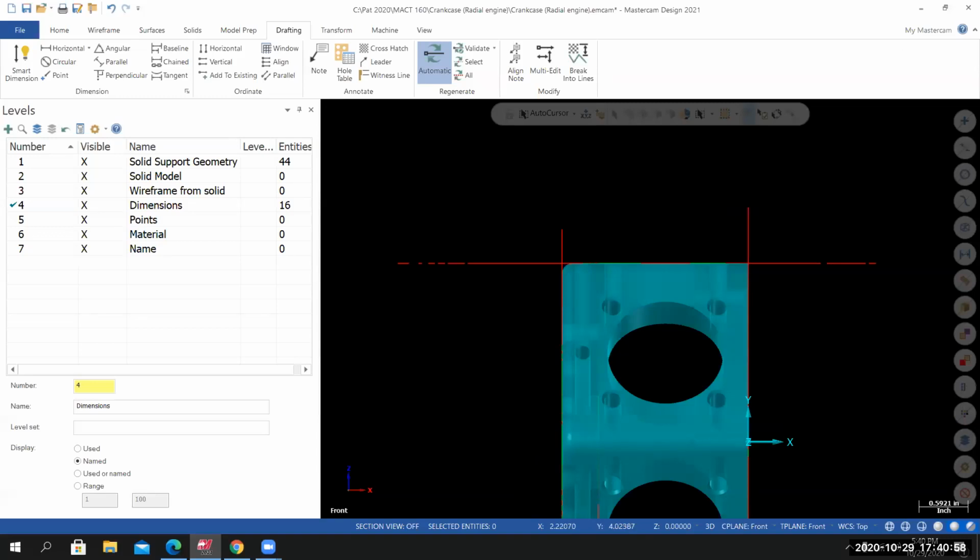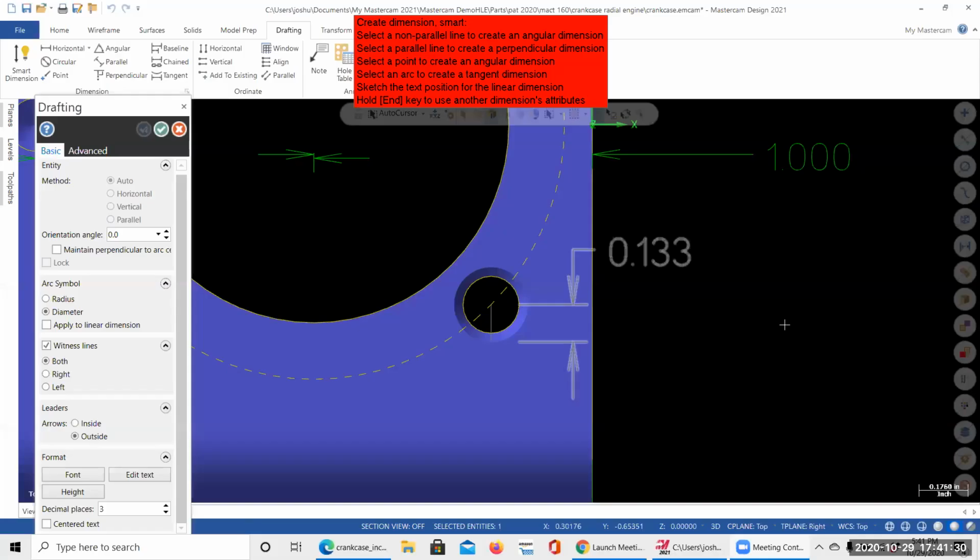Can I see your screen for a second? Yeah. So you've got to be careful not to let the auto cursor grab a quadrant or the center. So try to approach the circle from between the quadrants. If I can see your screen, I can give you a little bit of guidance on that. Yeah, I'm trying, but oh, my bad. That's on me again. All right, let's do this. Try it now. Okay, so hit escape. Trying, it's not working.